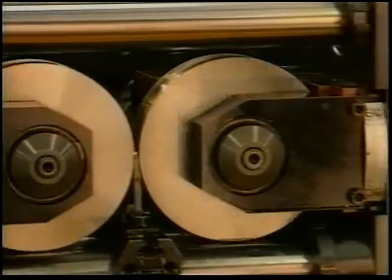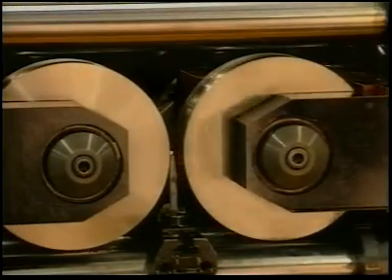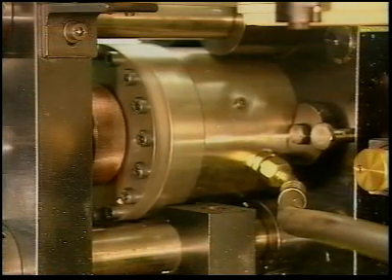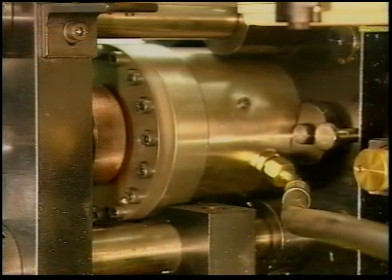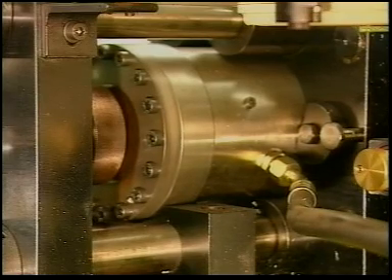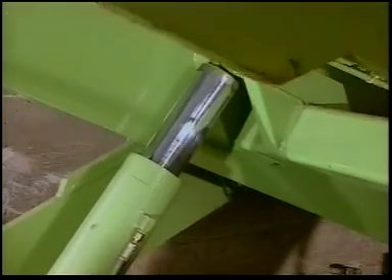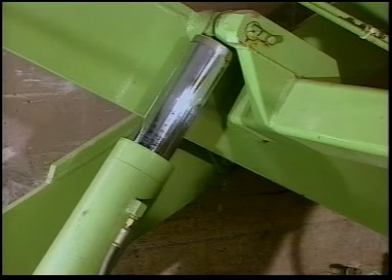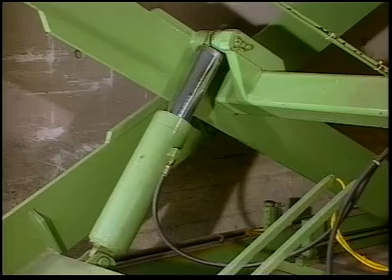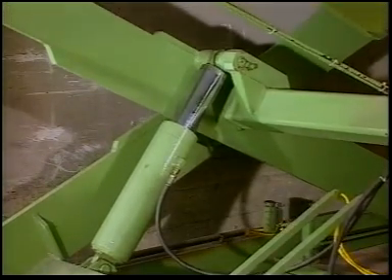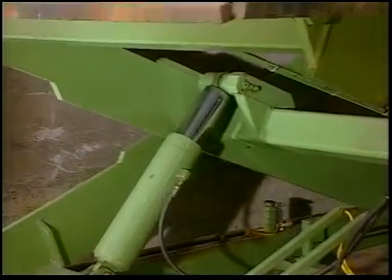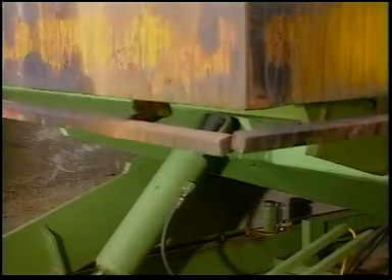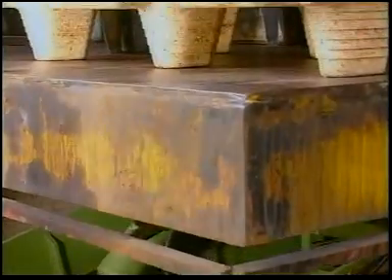But there are also single-acting cylinders with spring return. This cylinder, which creates contact pressure as it advances, is returned by a spring. The single-acting cylinder in this scissor-type elevating platform is a so-called plunger cylinder. Here the piston and rod diameters are the same. This design is extremely bend-resistant, which makes it particularly suitable for moving heavy loads. This is why plunger cylinders are often used in platform lifts.